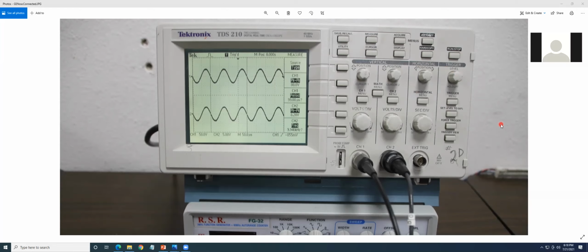After you got everything connected, that's when you press it. That's okay. However, they already connect everything, then sometimes you still have to press auto set measure. My question is when? When the wave signal is out of view, out of measuring view, you press auto set and measure so that the full cycle of the wave is in view.